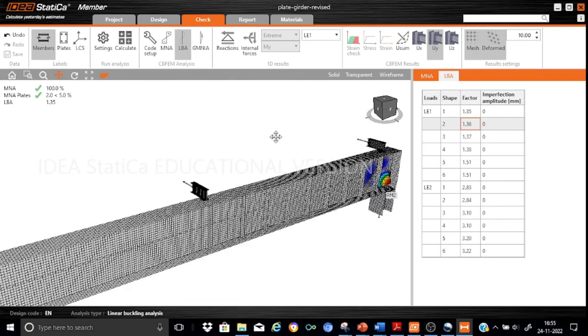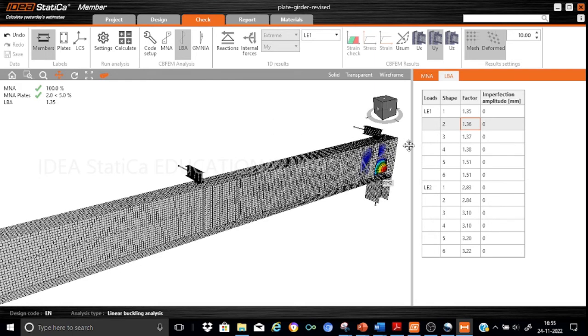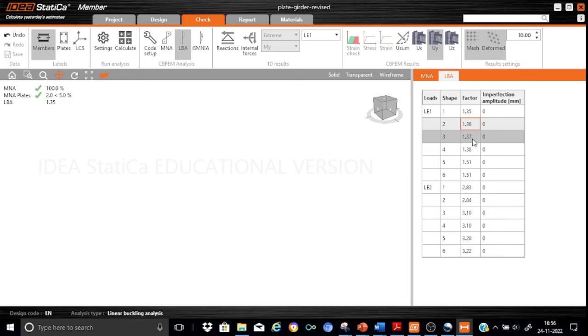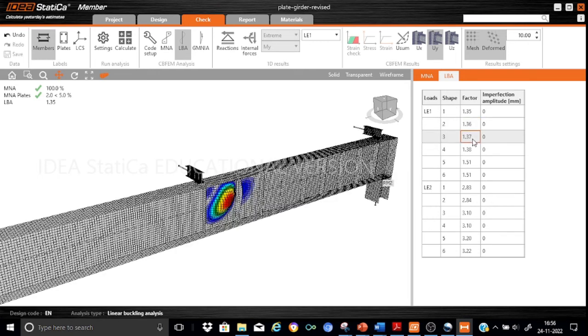So now that's all regarding 1 and 2. Then we have also got 1.37 and 1.38. That is also critical. Let us see which are these locations. We have designed it in such a way that the buckling is critical in almost all the zones, but we have got a very good margin, say 30 to 35 percent.